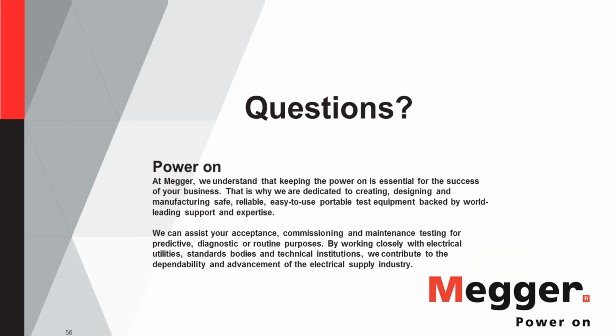Ideally, if you measure the ratio, it should be 1,000 to 1. But you're not going to measure exactly 1,000 to 1. There's going to be a difference, and that difference is directly a contributing factor to the magnetizing current. That's how you measure the magnetizing current.